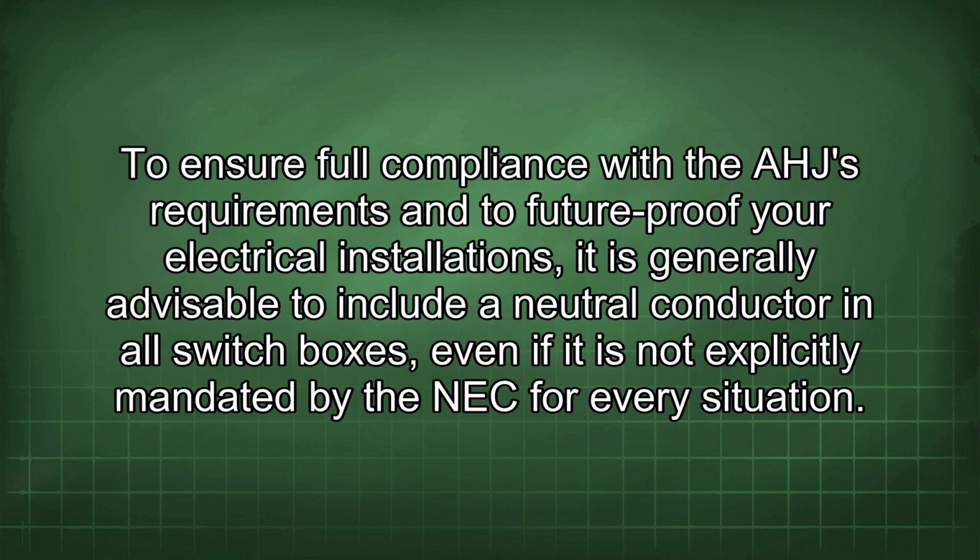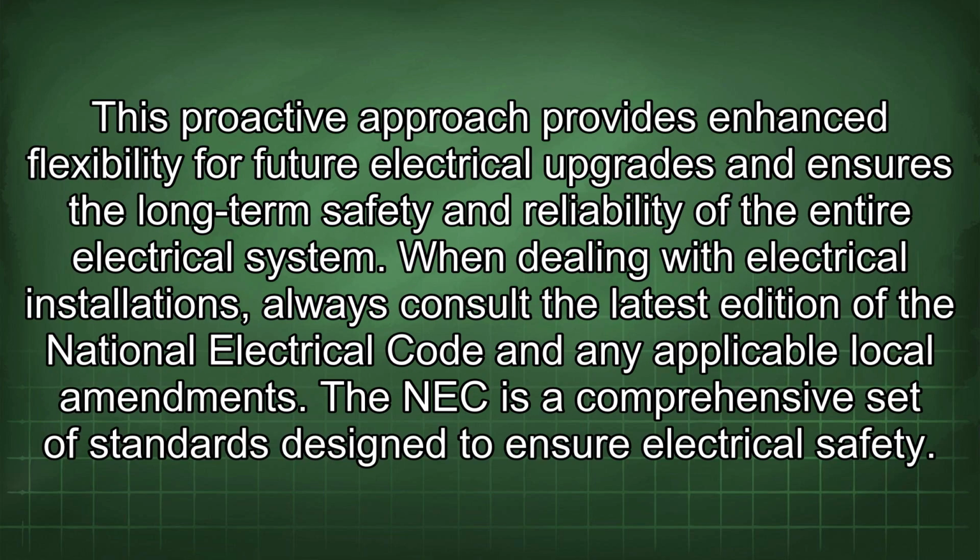To ensure full compliance with the AHJ requirements and to future-proof your electrical installations, it is generally advisable to include a neutral conductor in all switch boxes, even if it is not explicitly mandated by the NEC for every situation. This proactive approach provides enhanced flexibility for future electrical upgrades and ensures the long-term safety and reliability of the entire electrical system. When dealing with electrical installations, always consult the latest edition of the National Electrical Code and any applicable local amendments. The NEC is a comprehensive set of standards designed to ensure electrical safety.